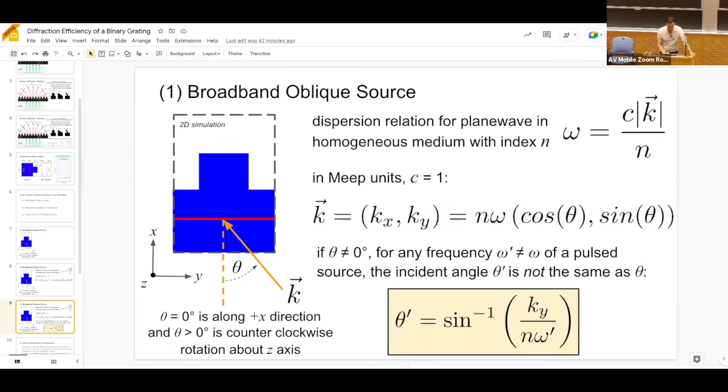There's a built-in routine in Meep called rotate that, given a vector, you can rotate objects around it. In this case, we're going to be rotating around the z-axis by some theta in degrees. And theta in is basically just the theta, which is a parameter in degrees, converted into radians. Now to actually set up the source, the source is going to have an amplitude function. So this source here is going to have this e to the i k y times y dependence, to generate the actual plane wave.